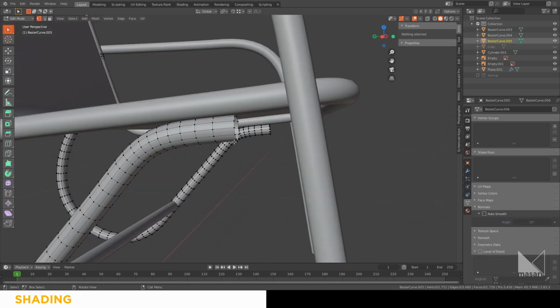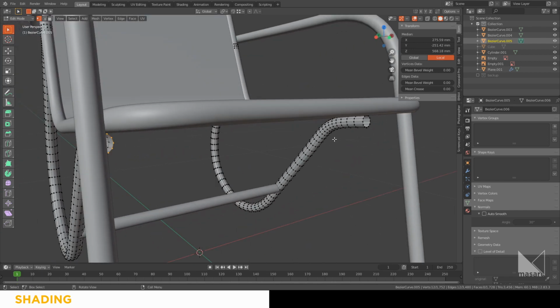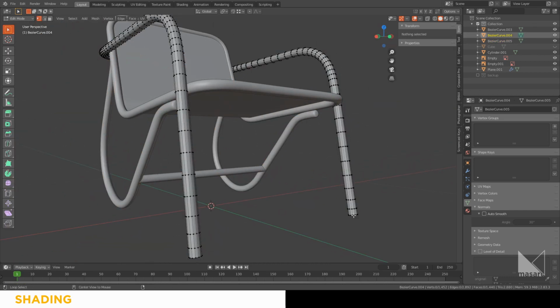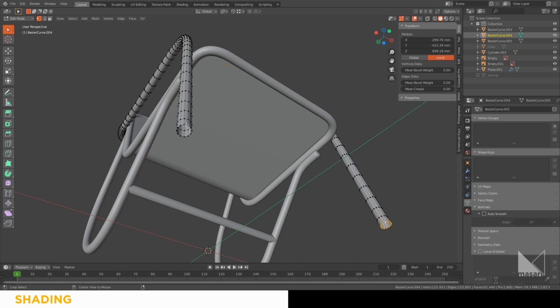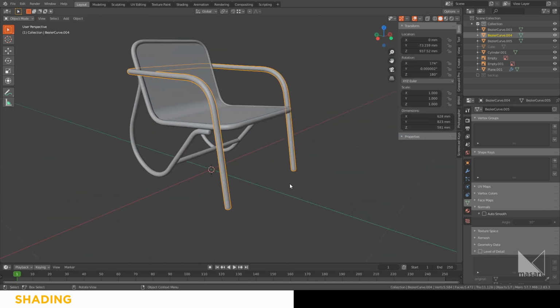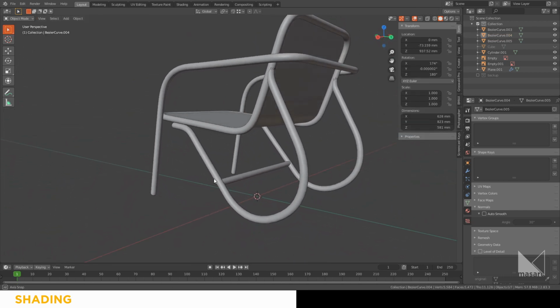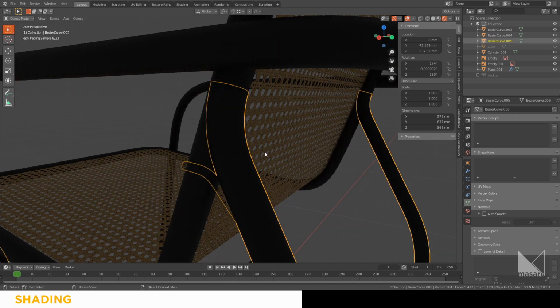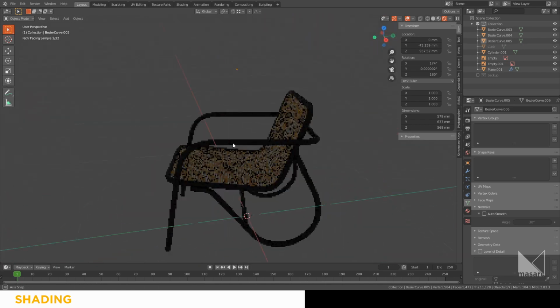and you can see it's already mesh. So I'm gonna fill those holes by F, and then Control B to make some roundness for the end here. I'll do the same thing for these. Hold F, Control B. Okay, that's pretty good for this one. If you're gonna render, it won't be noticeable.